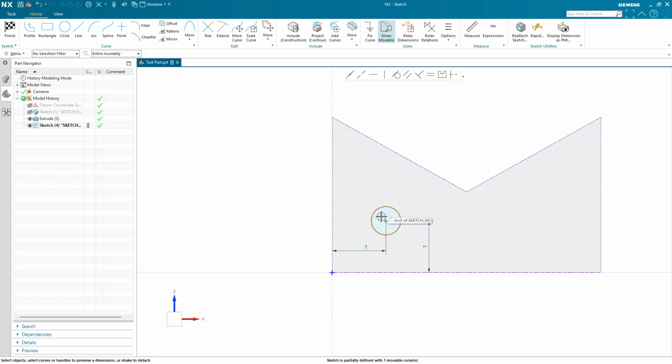So the last thing to make this fully defined, because it is a brown line instead of a black line, is we're going to set the diameter. That's just clicking on it typically. You can click and drag this as you need. And I'm going to set that diameter to 0.75 inches. And then we can do whatever we want with this. We can make it an extrusion that sticks out. We can make this a hole. All kinds of stuff will happen with that.